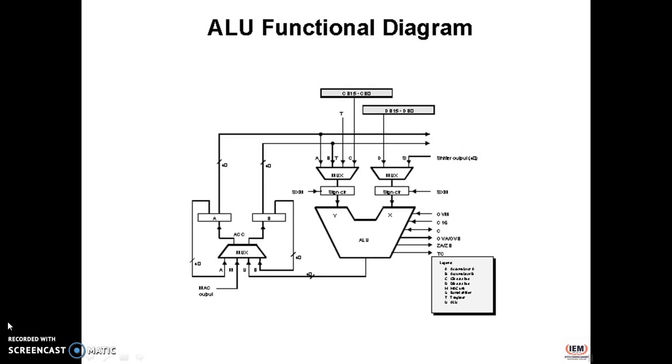The compare, select and store unit performs maximum comparison between the accumulator high and low word, allows both the test and control flag bit, that is called TC, in status register ST0 as in the figure, and the transition register TRN to keep their transition history, and selects the larger word in the accumulator to store into data memory.